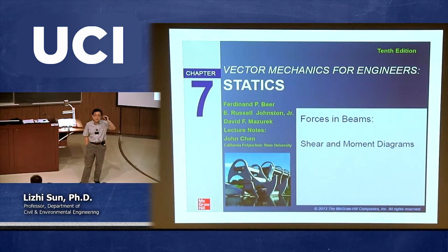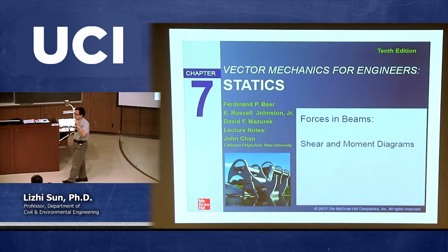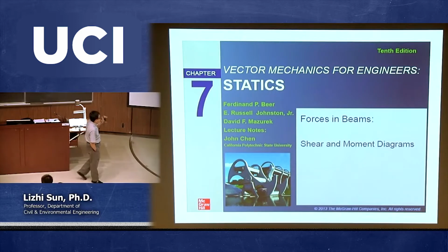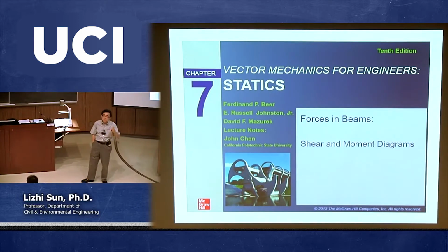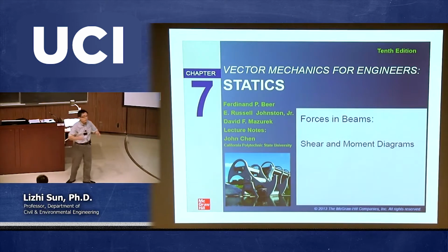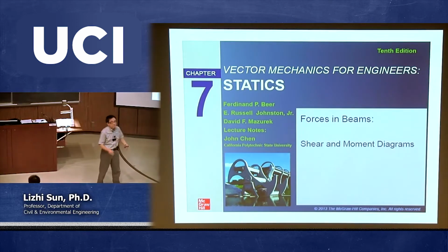So we are basically following a procedure. As a first step, we try to calculate the reactions for a given beam problem, because any beam must have supports, right? So obviously, we need to calculate the reactions as a first step.